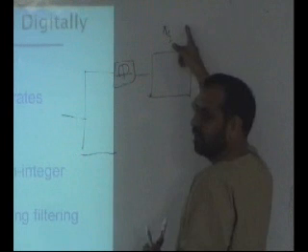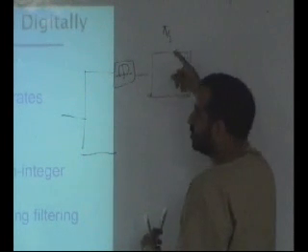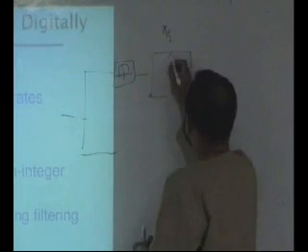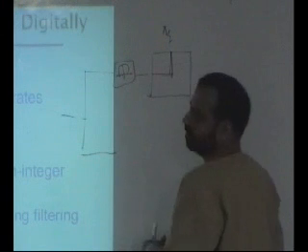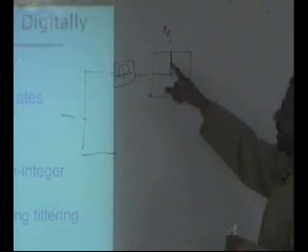Okay, so once you have this, you know there is a redundant sample after every sample, because the highest frequency must be pi, but now it is pi by 2. So you throw away every other sample. Once you throw away every other sample in x direction, every other sample in y direction, the image size is reduced to 1/4.